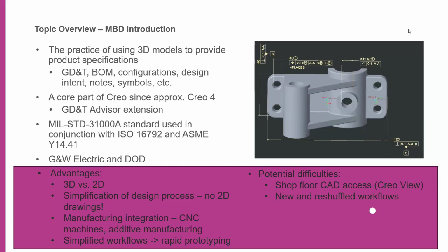So what that means in simpler terms is anything that you would previously do in a drawing, MBD is going to do that in our 3D model instead. So that can include GD&T, bill of materials, different configurations, design intent, notes, symbols, etc.